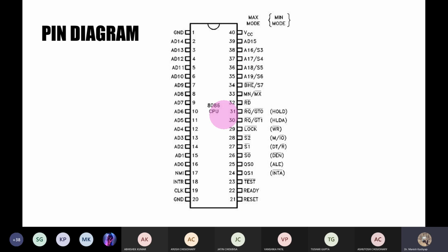The density of these ICs is increasing day by day, right? The number of transistors on this circuit increases day by day. So if the number of transistors is more, there is a chance that this ground voltage will not remain exactly zero because of the resistor connected between these two, or for that matter any electronic component connected between these two pins. There will be a similar connection between every other component and this ground pin. So there might be a possibility that this ground voltage will not maintain a zero reference voltage, right? With the increase in number of transistors, this problem comes.